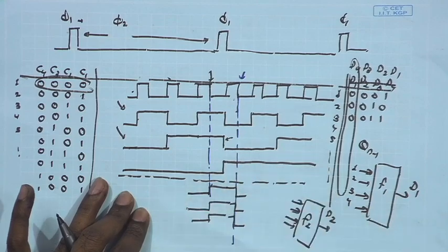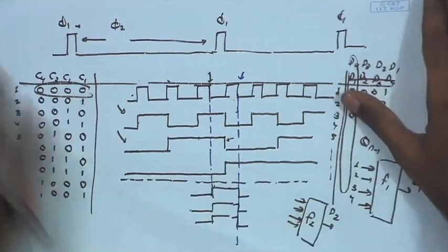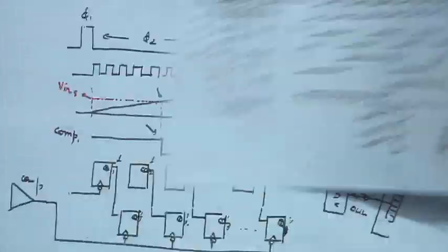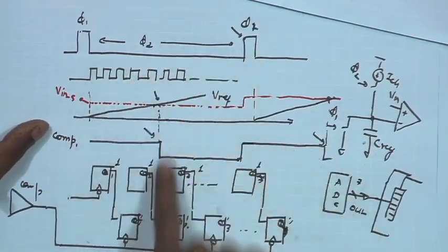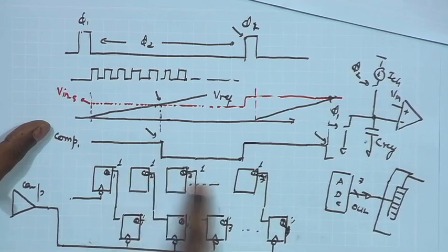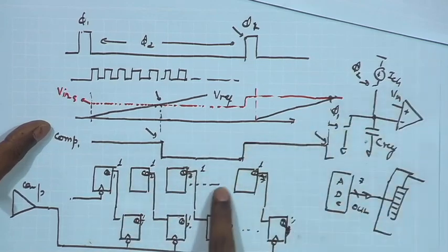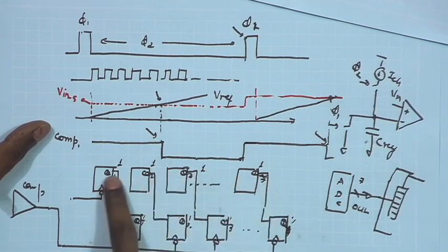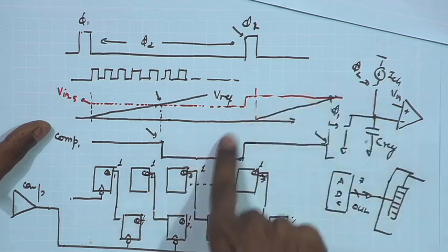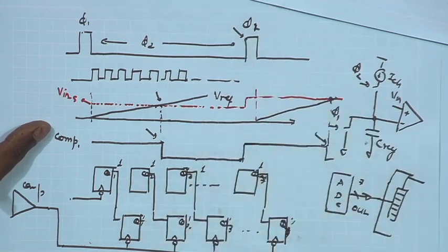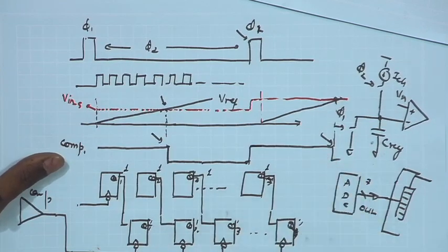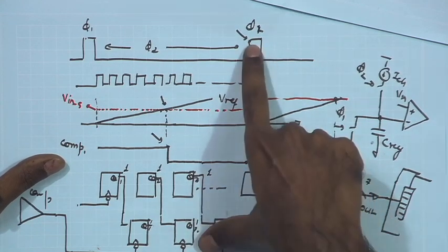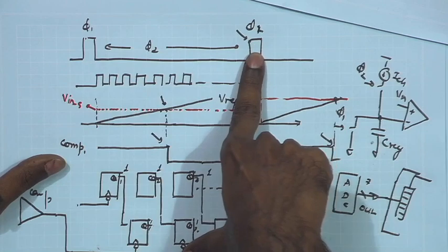Immediately after that, all of them will be transitioning to 0. So, this is the operation we expect, and therefore, if we simply allow the counter to run, if we simply allow these flip flops to keep running and keep counting till the maximum value 1 1 1 1 1, after that anyway all of them will be transitioning to 0, and that is going to give me the control signal for phi 1, meaning when should I set the phi 1 high.